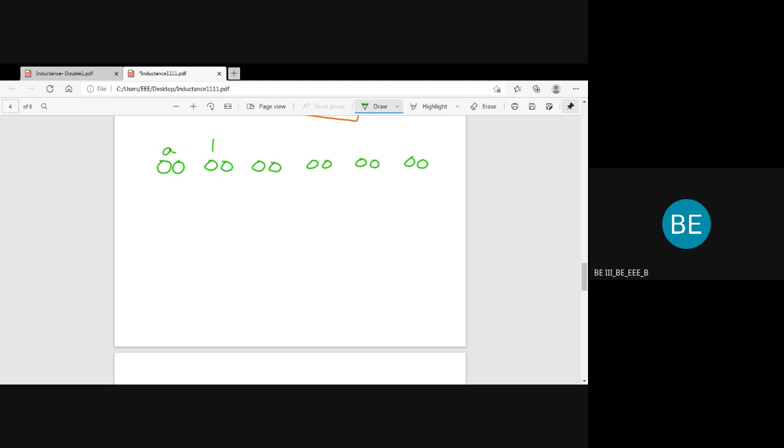So A, B, C, A dash, B dash, and C dash. So the distance between will be 2 for all the case. Radius of the conductor I am considering 12 millimeter, and the bundle spacing. So bundle spacing, I am consider it will be 40 centimeter.